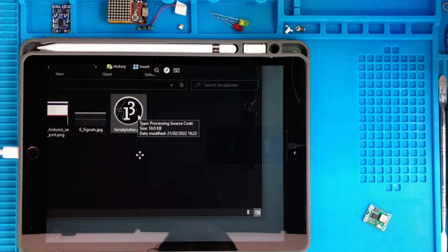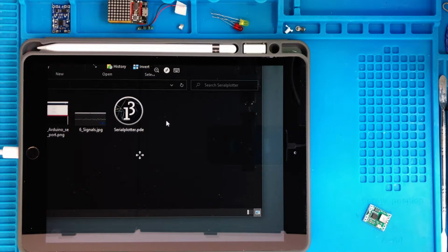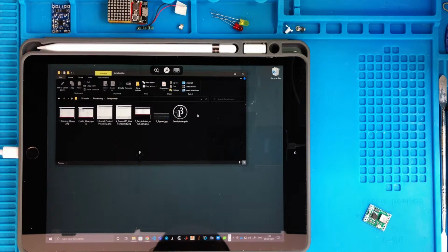Anyway, this serial plotter is a sort of software oscilloscope that will communicate via USB with the Arduino board. And in the Arduino board there is another software which makes the Arduino board become an analog recorder. So something that will record signals. It will acquire signals, we will see how, and then it will transmit via USB to your computer, where you have this other software that will plot the signals and save them as a txt file that you can later analyze in MATLAB or whatever.